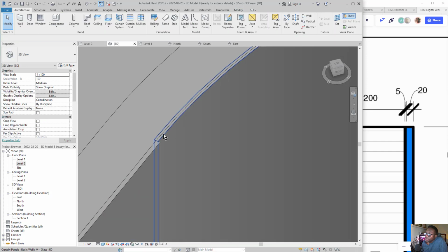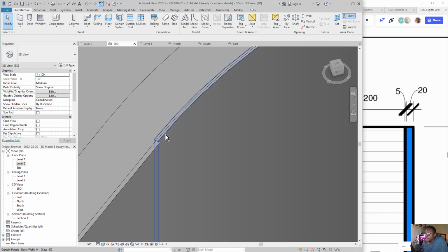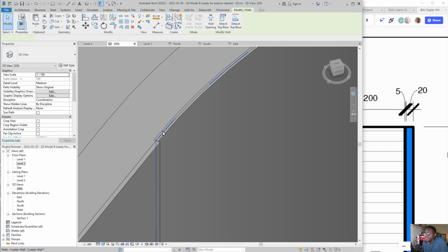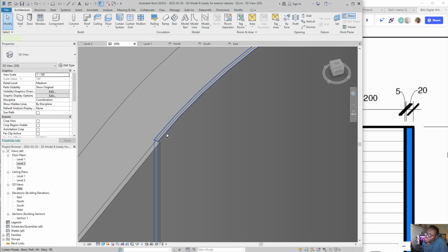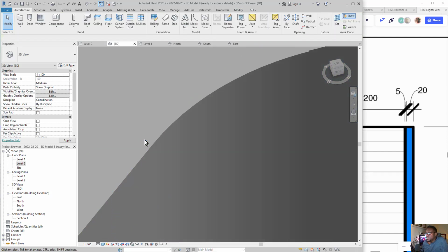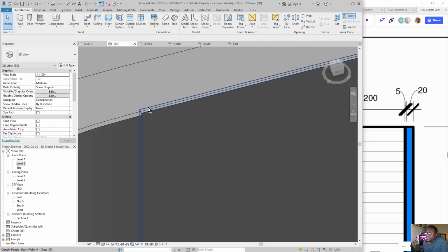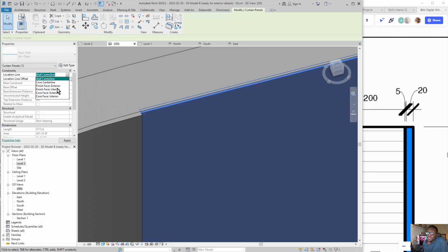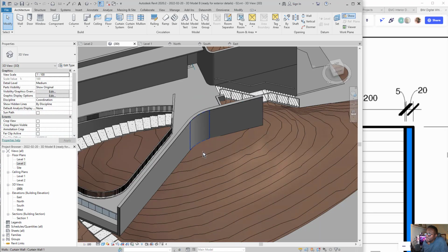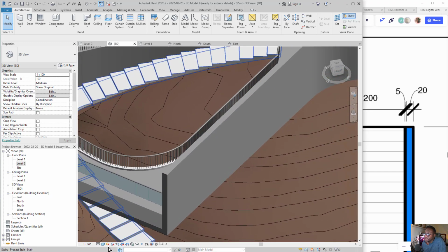I'm going to do the same thing for this. And what I'm doing here is actually selecting the panel, not the curtain wall. All right. If I click the curtain wall, it's going to say curtain wall, but I'm actually selecting the panel and then changing the justification. Now remember that this is really just a wall, but we are letting Revit think that it is a wall, but it's really glass. All right, so that takes care of having our outer layer there. There we go.